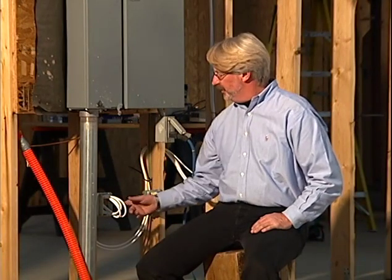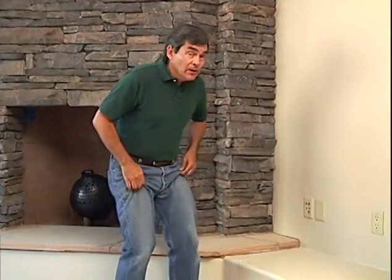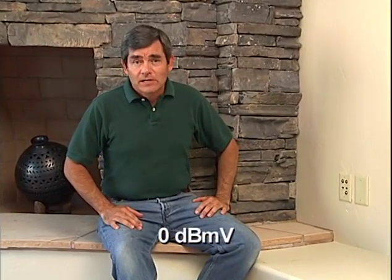The cable company's visual signal level at the NID or connection point at the house should not be anything less than plus 3 dBmV on any channel. This assumes a 100-foot cable run from the subscriber tap point of the cable system to the house. Now, the signal level in the house at the point of connection of the customer's equipment should not be less than 0 dBmV on any channel.